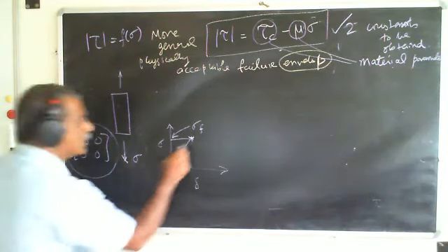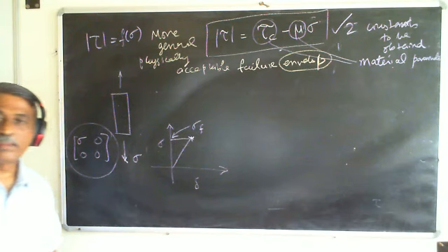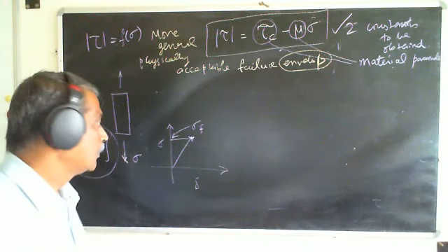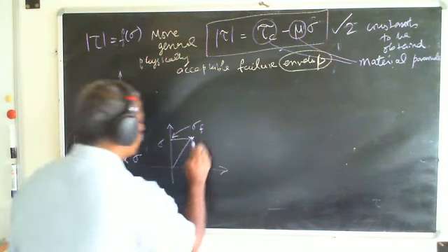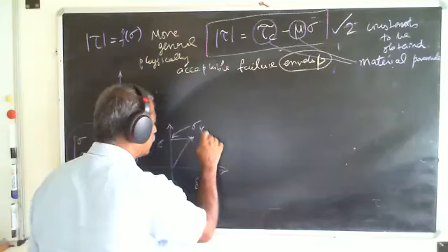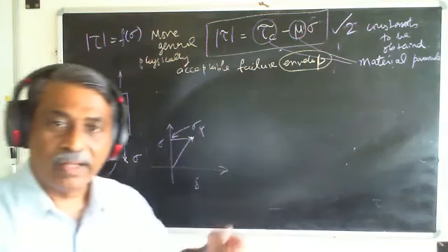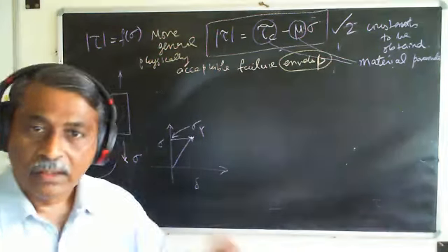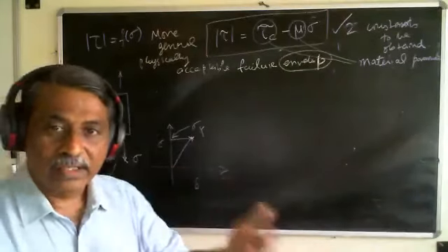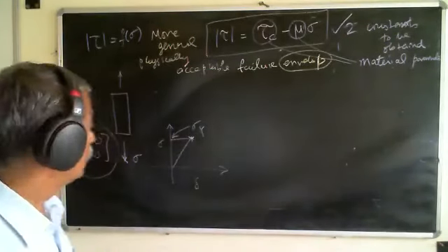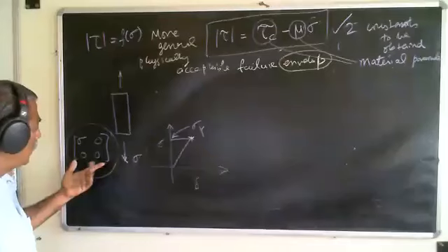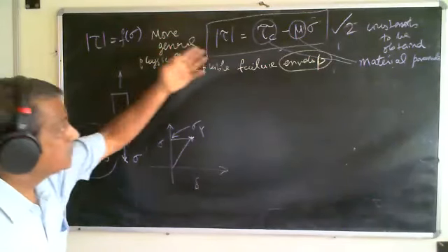And I found that it is failing at sigma equal to sigma f. If you want to call it sigma f or sigma y, it does not matter. It depends on whether it is a ductile material, where we say it is yielding, or a brittle material, where it is failing or breaking into two. Now I relate based on the equation.